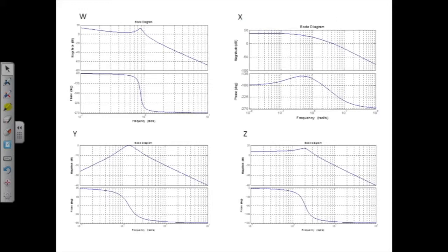Do you want to change your mind? So I've got an oscillatory second order system that's lightly damped. So let's go through these. This is starting off, it's got a slope to begin with, so that's rubbish, isn't it? That's no good to me.